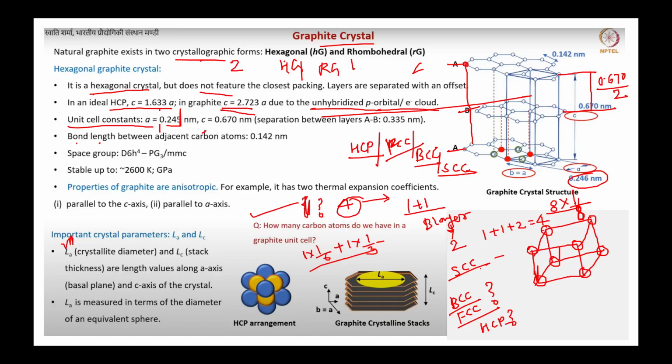So this is one atom. Suppose how it will share on this side. One will come this side, another on top of this, another here. So one, two, three, four, and the other side will also be the same thing. So the total will come to 4. Again, for the BCC, the atom at the center is not shared with anyone. So for the 8 corners, 8 into 1 by 8 plus 1, so 2.